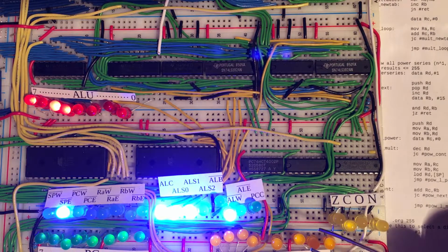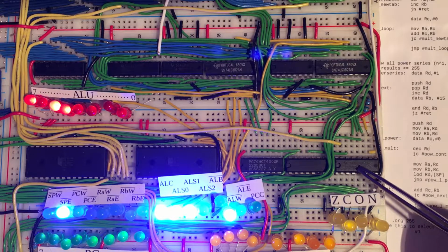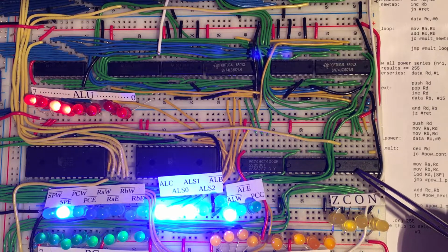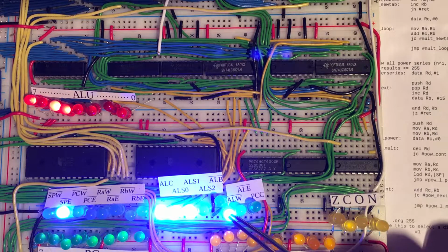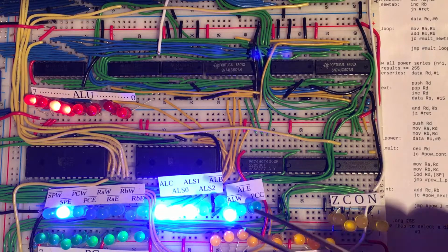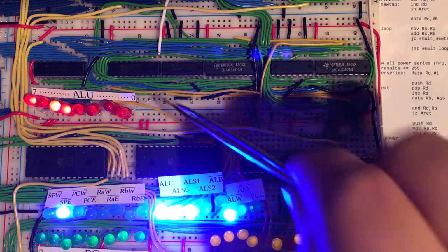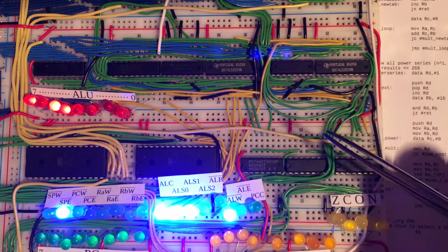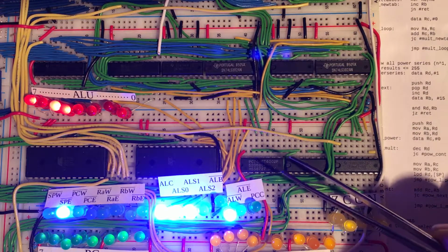And then finally, we have the flags over here in the corner, and so they too have a register chip, which is in fact a 74HCT173, which is a 4-bit register, because we only have 4 flags. And so that too will be written whenever it's being told to do so by the control unit. And as you can see right now, the ALU is about to perform an operation, because the ALU write signal here is being asserted. So these register chips for both the flags and the ALU result will latch the result of some computation as soon as the next rising clock edge arrives.